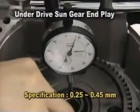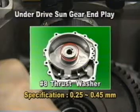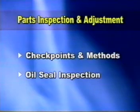If the measured value exceeds the specification, change the number 8 thrust washer with one of the 10 different washers in thickness. Number 8 thrust washer is between the rear cover and reverse clutch. Lastly, oil seal inspection will be explained.